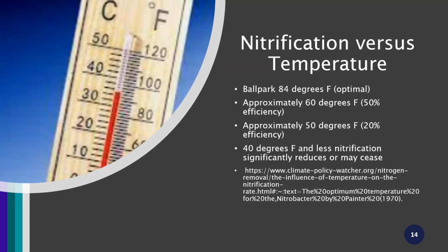And especially, we're located in Wisconsin, in the colder climates, when you get into the real deep freezes in February and January, it takes a lot higher MLSS concentrations and higher SRT values, because the lower temperatures just basically slow down all those biochemical reactions.